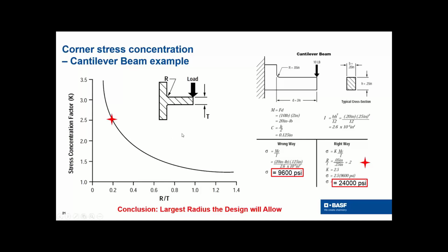So let's go to stress concentration. Another important attribute for plastic, and it doesn't only apply for plastic. Stress concentration is for metals and plastic equally, but for plastics, most of the time we're designing with a smaller factor of safety. So in that case, stress concentration is usually more important because of that.